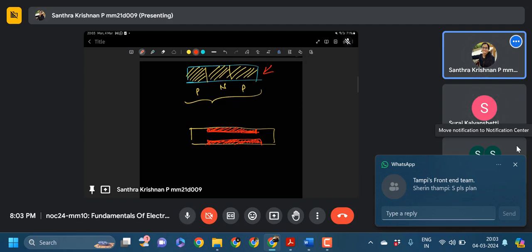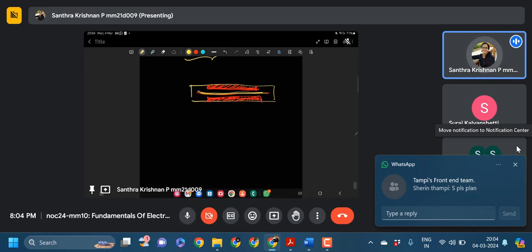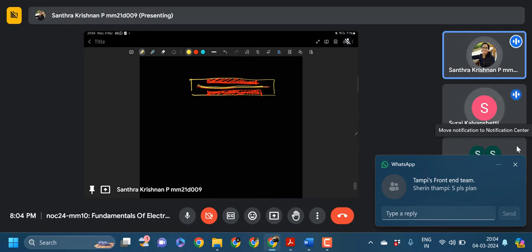And in JFETs, current flow takes place through a channel in the device. What is this portion called? Channel. Yes, it is a channel-based device. Depending on the external bias we use, we can pinch off this channel, or increase or decrease its width. If you apply too much voltage, sometimes pinch-off happens and the channel will be lost.